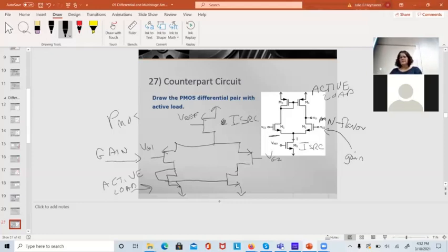These are little games people play with these little differential pairs, and they turn them into op amps, and they get used all over the place. If I need a comparator inside a memory circuit, I have two choices. I can either put a latch in there, or I can put a diff amp. And I can put a better version of it by putting a P-sense and an N-sense amp in there at the same time. All of this gets used in what we all consider to be digital circuits.